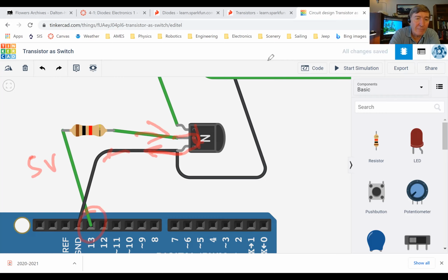I'm even going to put a resistor here, so we're just going to have a tiny trickle of current. It might not even be 1 milliamp. It could be a milliamp, but a tiny trickle of current is all we need going through here. Once we do that, that turns the transistor to the on condition, and that allows a very large current to flow through here.